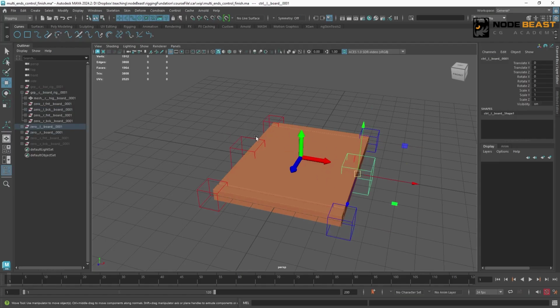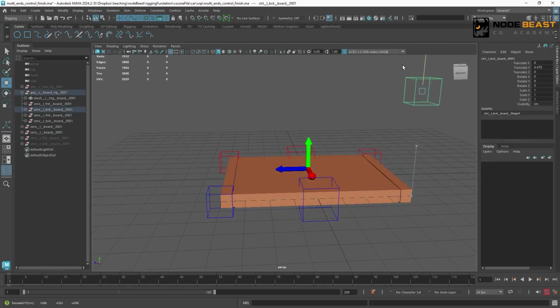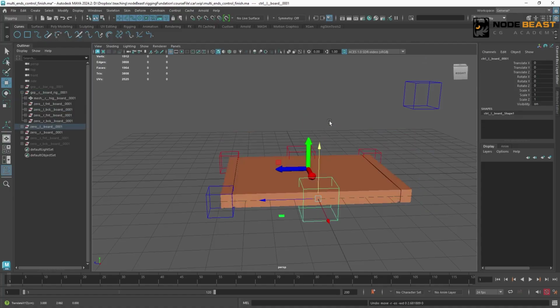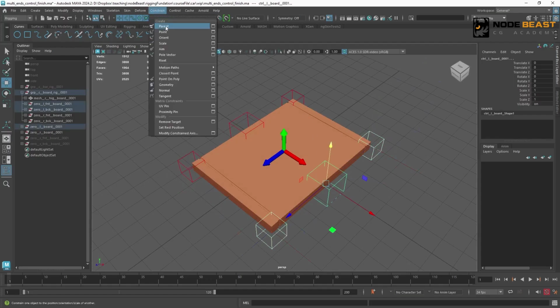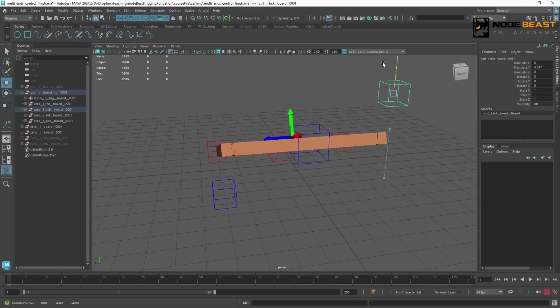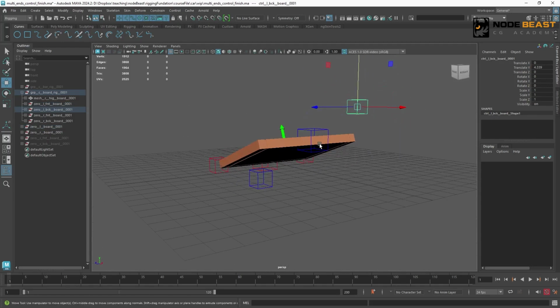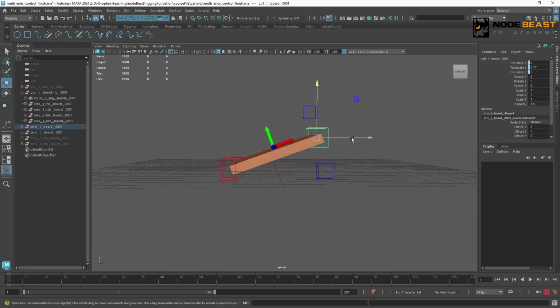We can think about where the middle controller's position should be. When we move one of the left side controllers up, it's definitely going to be at a position between these 2. So look here. If I select these 2 controllers and apply a point constraint to this middle controller, this way, look, when I move one of the controllers, because it has a 50% influence on the middle controller, the middle position will be at the 50% mark between these 2 controllers, and it will create this tilting effect.